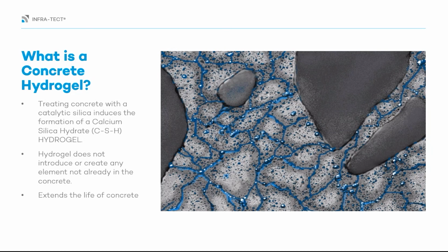So we spray the concrete, ideally the day of the pour. That penetrates right into the concrete, 150 mils actually. It's not like a lot of curing products or sealing products that sit on the top of the surface. It penetrates right down 150 mils on most concrete. And what that does is fill up those pores and you start to get that reaction, and it first forms a hydrogel that blocks all those pores within the concrete.